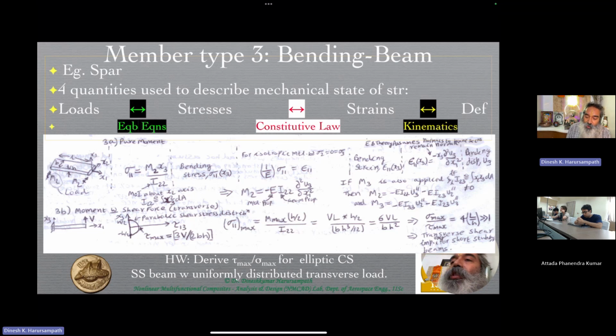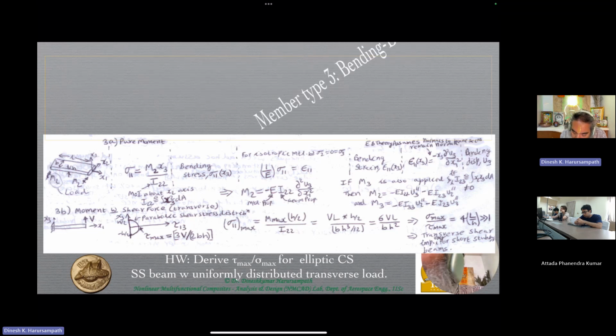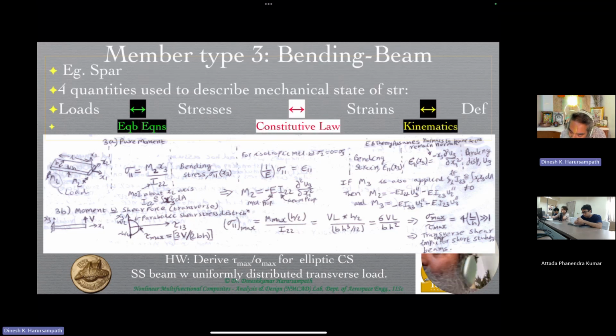as part of the structural analysis course, which is why an I23 comes in here, which is the product of inertia. So you see over here that this I23 is a product of inertia. Just like you have x3 squared dA as I22, x2 squared dA will be I33. We'll also have an I23, which involves an x2 times x3 times dA. This is something that you would have studied as part of the dynamics course AE2240. So something which is coming out of that. So this will be non-zero because it's an asymmetric cross section. There are no two planes of symmetry.